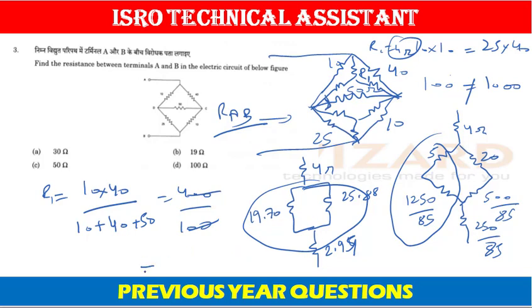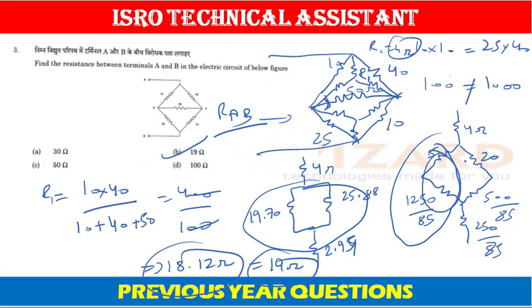On calculating this, we will get around 18.12 ohm. This will be approximately equal to 19 ohm. This is how we can calculate this question, and this is a very important question. First of all, we have to convert delta into star, then some connections are in series, some are in parallel, and after that they all are in series. So option B is the correct answer.